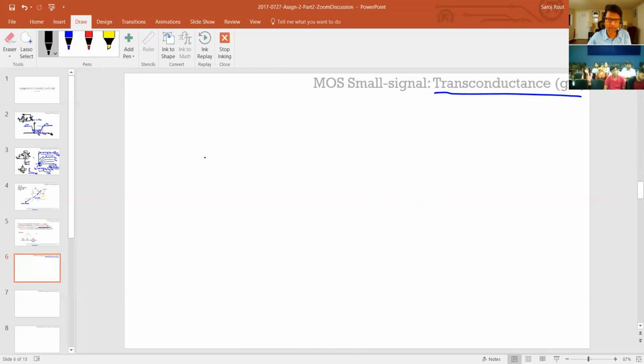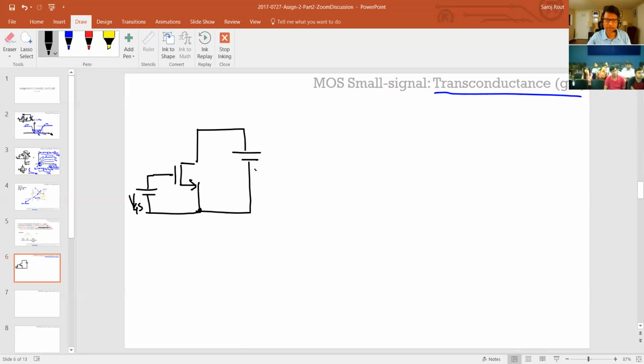essentially, so if you take an NMOS transistor, for example, so we said, we take NMOS, and we said for it to be in the active region, we bias, like before, a certain VGS, which is greater than VT, and we apply a VDS. And typically in these cases, the source voltage is connected to the ground, but may not be so, right? So that your source to bulk voltages.